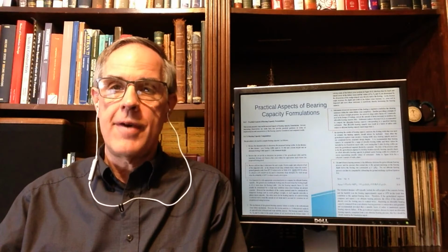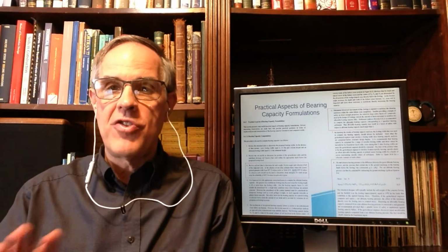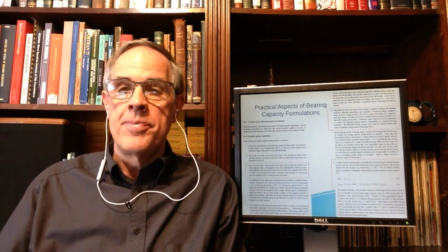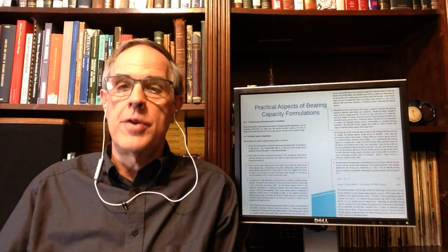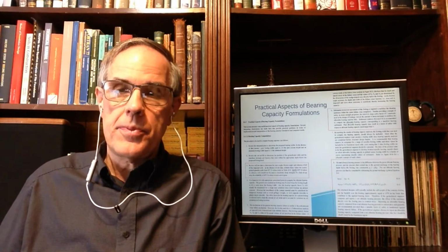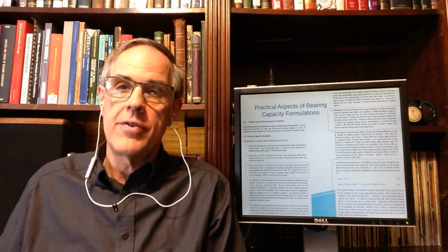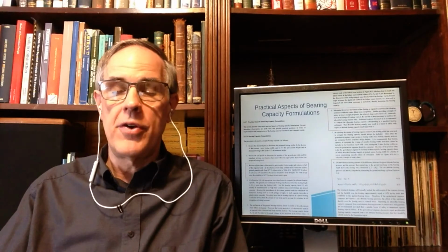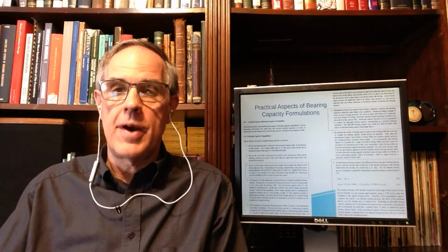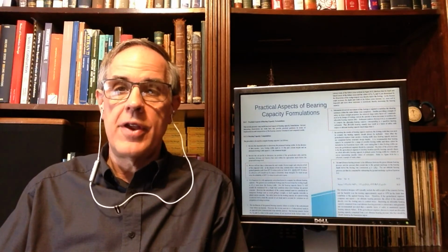It should be obvious by now, no matter what variation of slope stability or bearing capacity equation you're using, that the Mohr-Coulomb triple, the unit weight, the cohesion, the internal friction angle, plus all the other things, the groundwater table and the general stratigraphy, are essential to know to design a foundation properly. And the soil foundations are no exception.